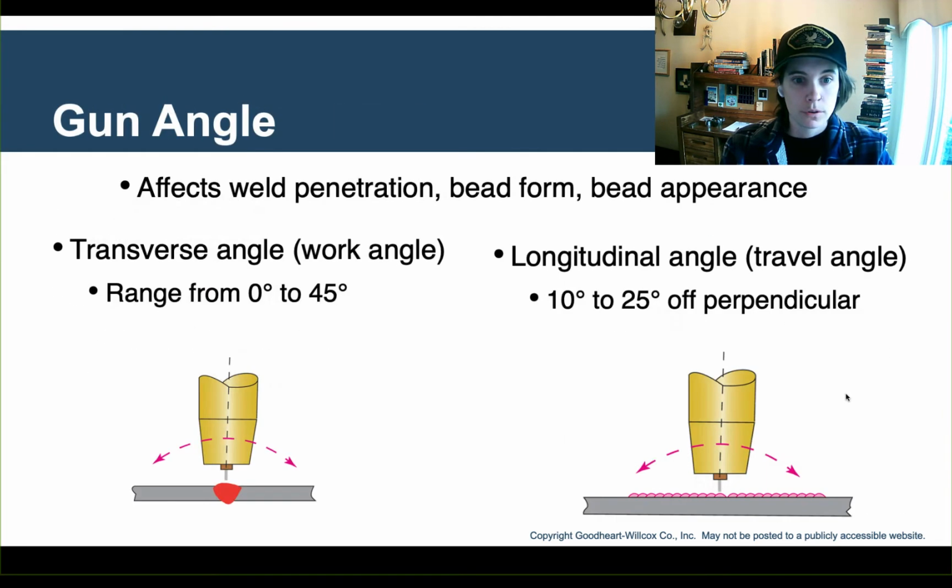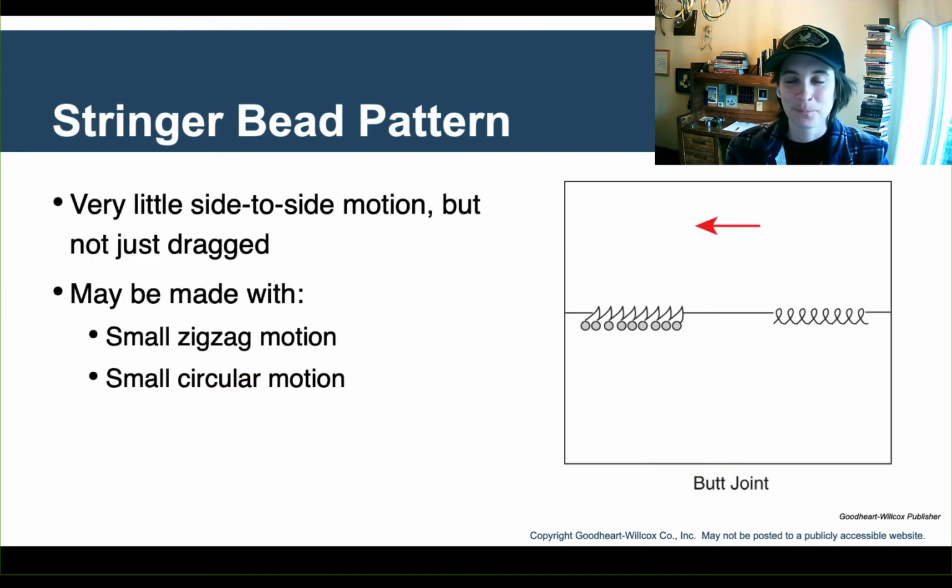Angle. So work angle and travel angle, or transverse angle and longitudinal angle. Do try to remember those. At least just keep in your head that those angles matter and how to adjust them yourself, even if you don't remember the names of them.